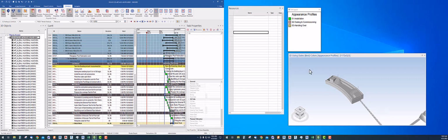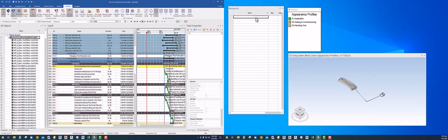Now in this sheet I have written the resources which need to be created in general. So first of all, I'll create a blank resource by right clicking and choosing add equipment. And then write bedding layer. If you want to rename, just double click after a pause and then you can rename.